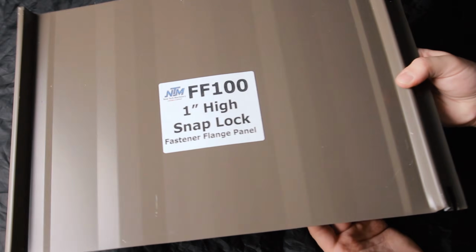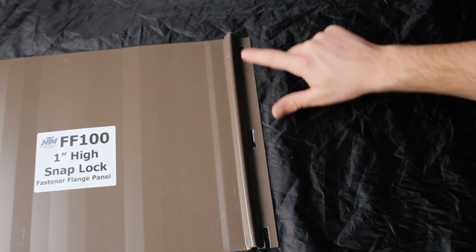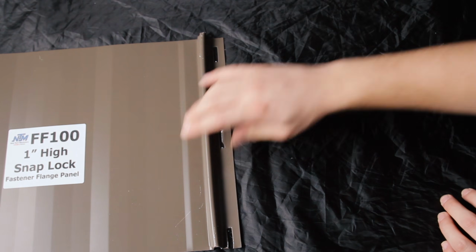On a side note, I say most standing seam assemblies use clips because there is a common hidden fastener residential system that does not use clips, called a nail flange panel. It relies on the screw heads themselves to hold down the panel, as they are fastened directly to slots in the metal.